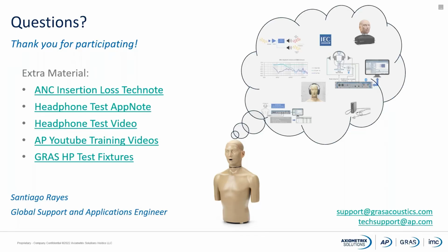The bottleneck for the measurement, as I mentioned before, is the noise floor of the combination of microphone capsule, preamplifier, and ear simulator. If the noise floor of your system is 20 dBA and you are trying to measure a signal of 50, then you won't be able to measure that signal because it will be masked by the noise floor of your system. So it doesn't matter if you're using an octave analyzer or an FFT.